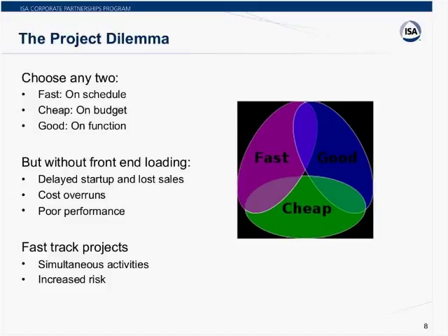The one that I always dread is, for the types of processes I've worked with, they're higher hazard processes, and we're doing a process hazards review or a process hazards analysis, a PHA, and that PHA will get put to be done in parallel with the design. And so they're modifying the design as we're doing the PHA with the design information to try to identify, do we have adequate protection from our hazards? And that always ends up to be a challenge to try to get the right information at the right time of the project.